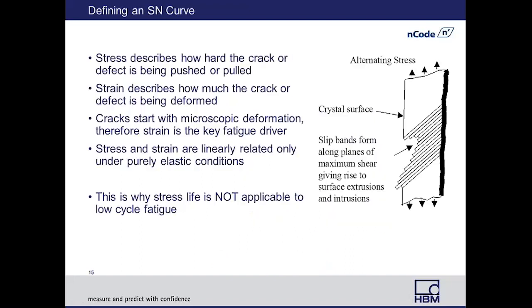On to strain life. So slightly different. With stress life, we made the assumption that stress describes how we're going to model our fatigue analysis and the crack initiation. Stress actually describes how hard a crack or defect is being pushed or pulled apart. Strain, however, allows us to describe how much the crack will deflect. So we're going to be controlling it on strain.